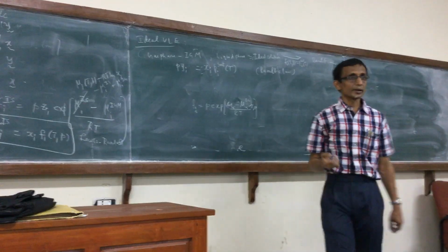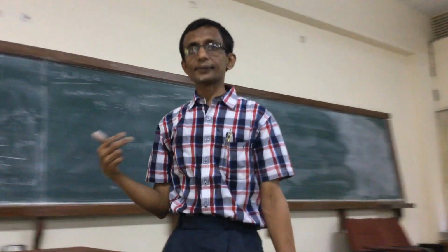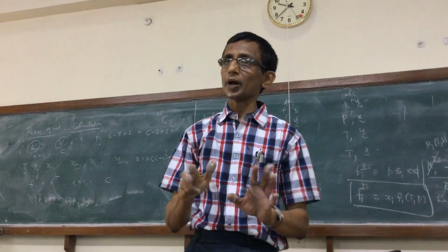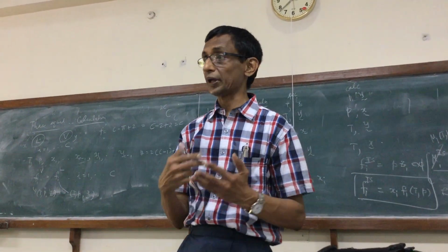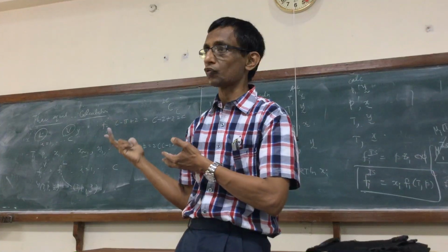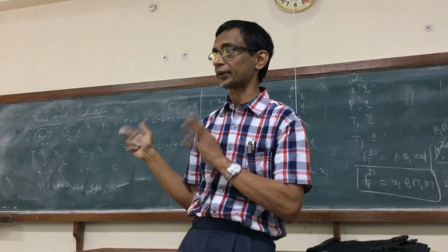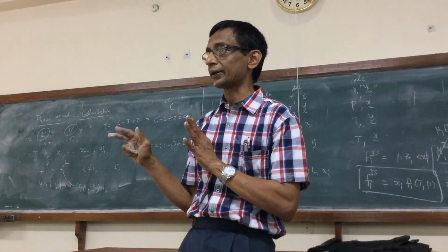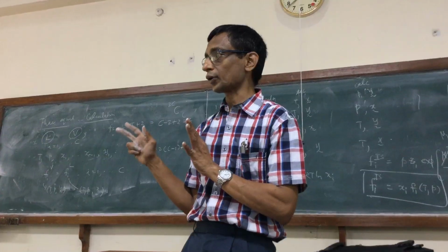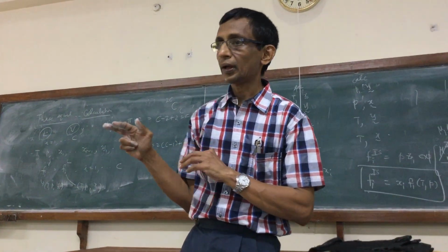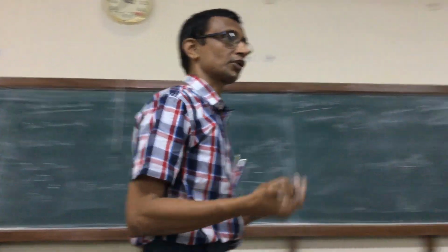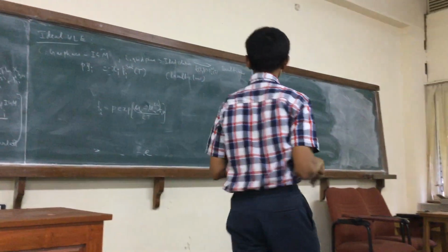The Raoult's law considers the gas mixture as an ideal gas mixture, and the liquid as approximately an ideal solution, with the additional simplification. This is a big simplification because otherwise I have to use the equation of state to calculate the fugacity. But Pi sat is readily available through the Antoine equation and so on. Right? So we reduce it from a function of temperature and pressure to a function of temperature.